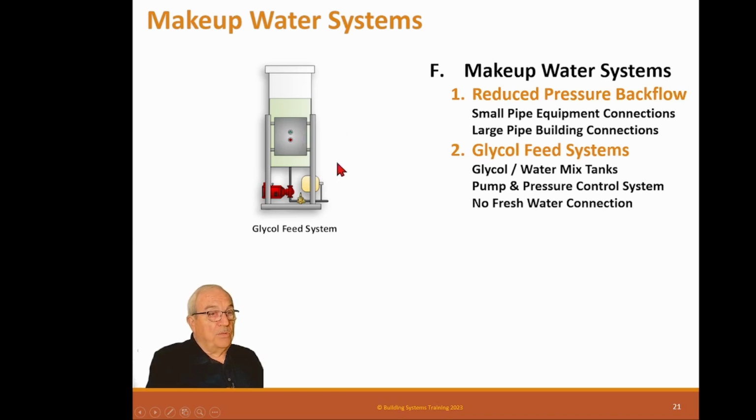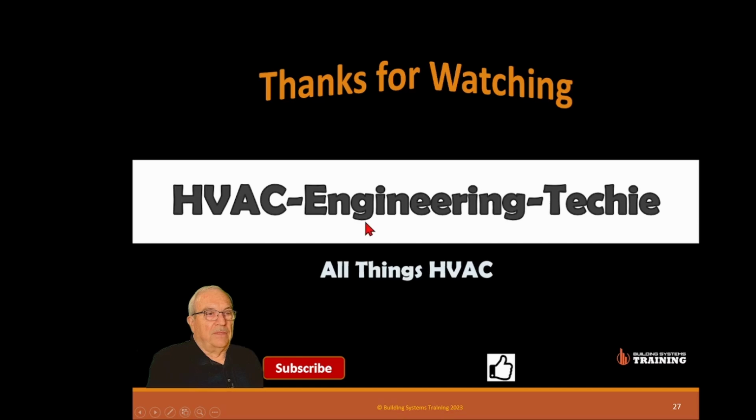But the reason we don't have these connected to the water system is because if the water in the chill water system leaks, and it gets filled up with fresh water, and the operators don't know it, it'll freeze. So what happens here is we make them keep an eye on this tank, because we never allow it to automatic fill. It's always filled manually from this tank. Made it through this system.